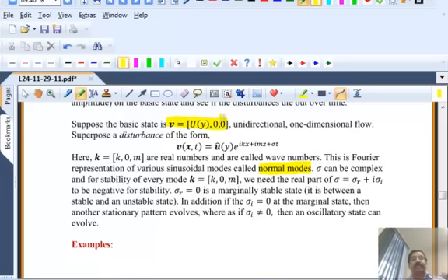And the perturbation flow, exactly as we did in the previous case, can now be spatial. That adds complexity to it. We have looked at only ordinary differential equations. Now we are looking at partial differential equations. So the perturbations would be spatially varying, and we are going to capture that by this kind of an expression: e to the power i k x, e to the power i m z, and e to the power sigma t. Those are the nature of the perturbations, with y as the unknown.